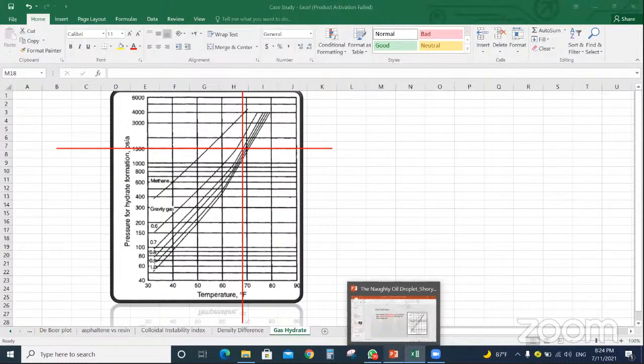Why is this restriction occurring? Due to the deposition of some solids coming from the hydrocarbon phase, like the asphaltene, the wax, and the gas hydrate, and any others, and some deposits due to the interaction between the formation water and the injected water, like the scale.